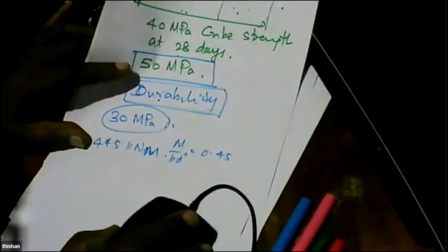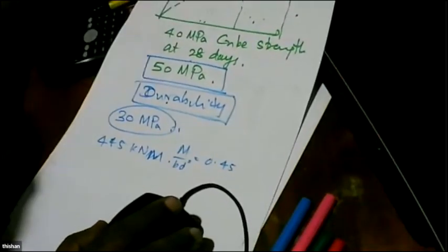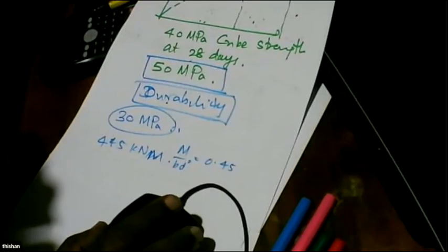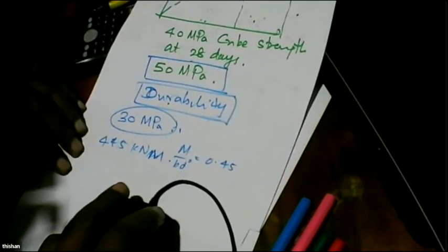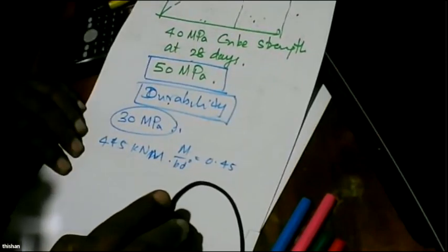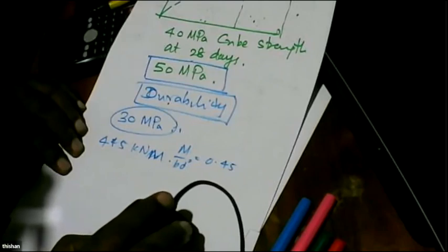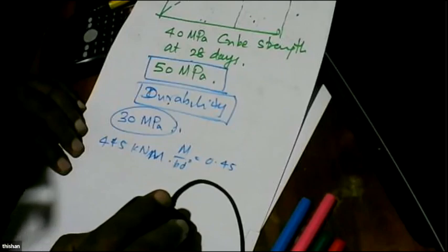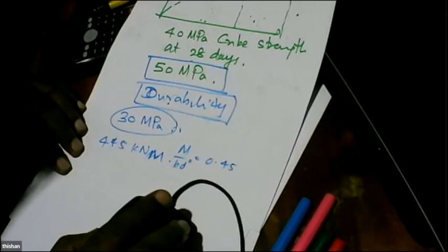Any questions? Yes, at the very beginning, there was a question: what is the basis for choosing 1.75 meters as the beam spacing? So actually, I wanted to use 3.5 meter wide lanes for the vehicles. Because if you look at the type of vehicles that we use in our roads, our buses are 2.4 meters wide.